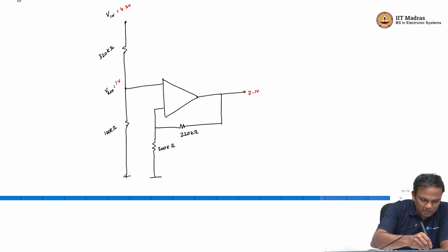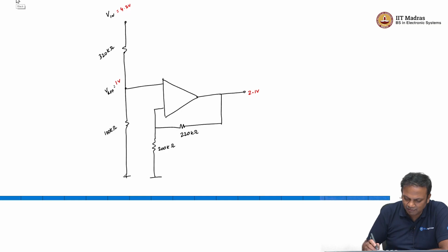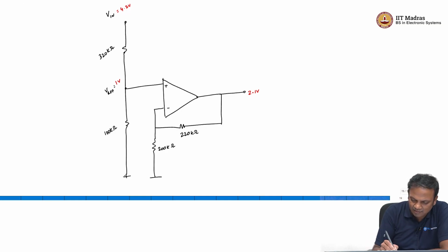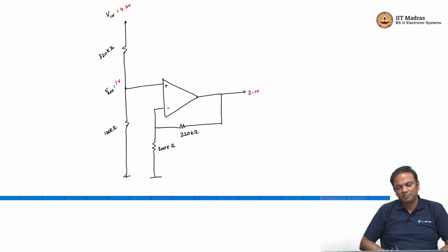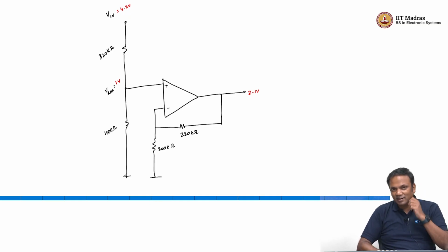Now, let us put the signs for the op amp. We need negative feedback, the only inversion comes from the amp. So, this has to be negative, this will be positive. Now, we saw this with the battery charger also, and you have seen this earlier in the course as well, that now the output impedance is going to become very small because the loop gain is going to come and help you. So, R out divided by 1 plus loop gain will be the effective output resistance.